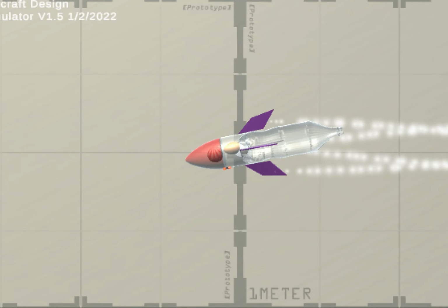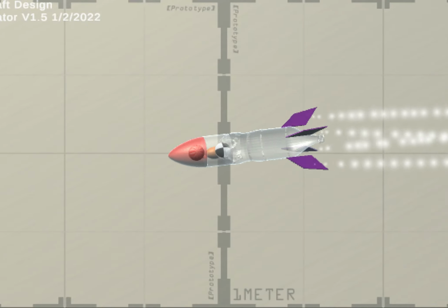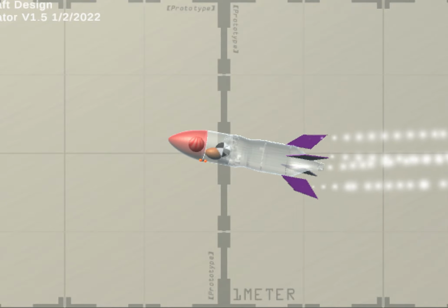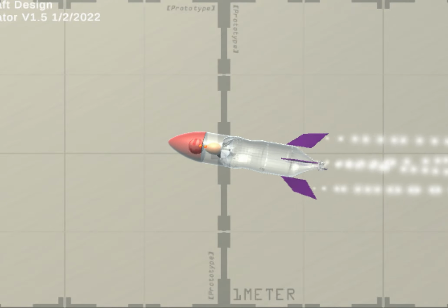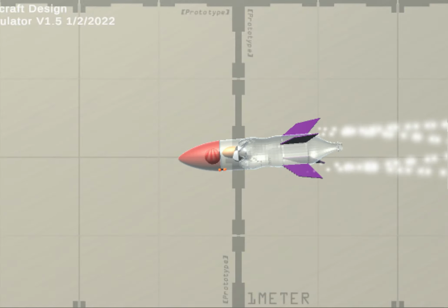With the help of simulation software, we can optimize a rocket to meet the design criteria by making adjustments to the fin position, shape, and number of fins along with the shape of the nose cone. It is important to have a stable rocket to ensure the rocket has both a controlled climb and descent. Making changes to these parameters helps you to make an informed decision and make multiple versions of your rocket, each better than the last.